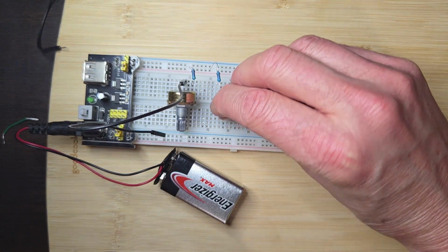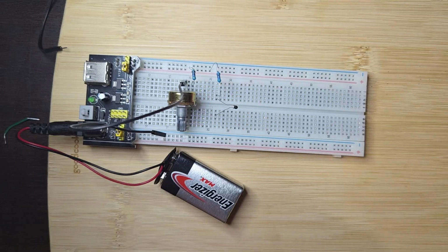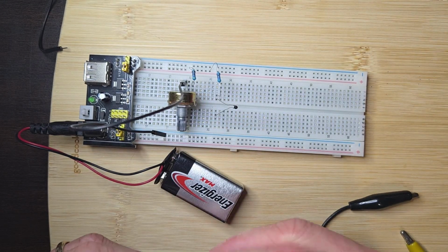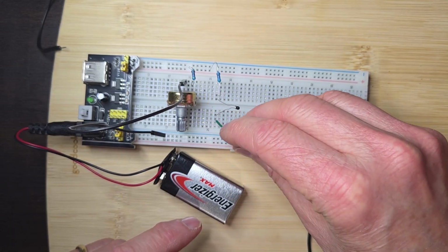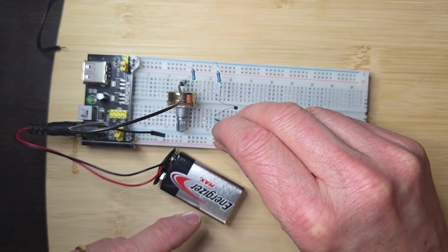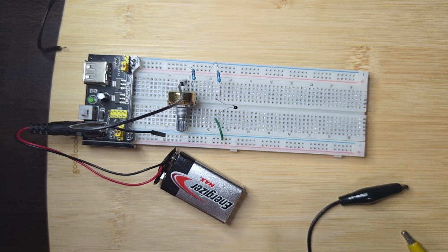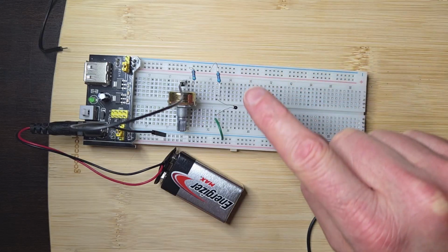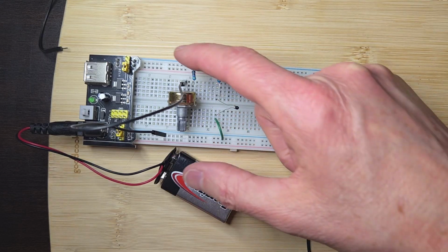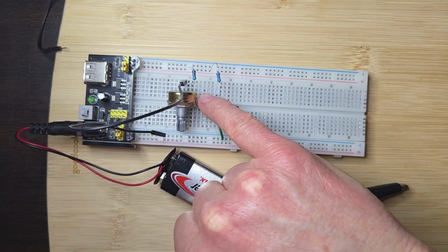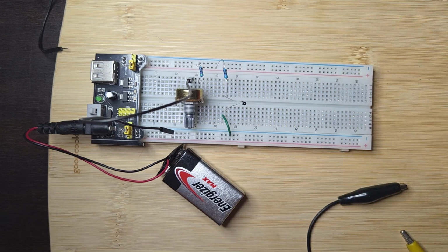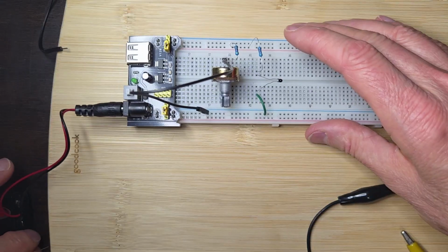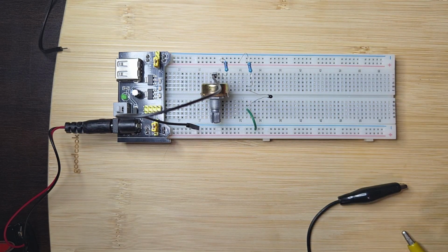But what I'm going to do is wire up the thermistor first, and show you how to do that. So I've got it here, and then I'm just going to put a little wire here and then run that into ground, like that. So now I've got current flowing through this resistor, through the thermistor to ground. I've got current flowing through this end of the potentiometer to that little wiper thing where I can change the resistance to here. But I've got to add a little bit of resistance to this potentiometer so that I can match the resistance of this guy.